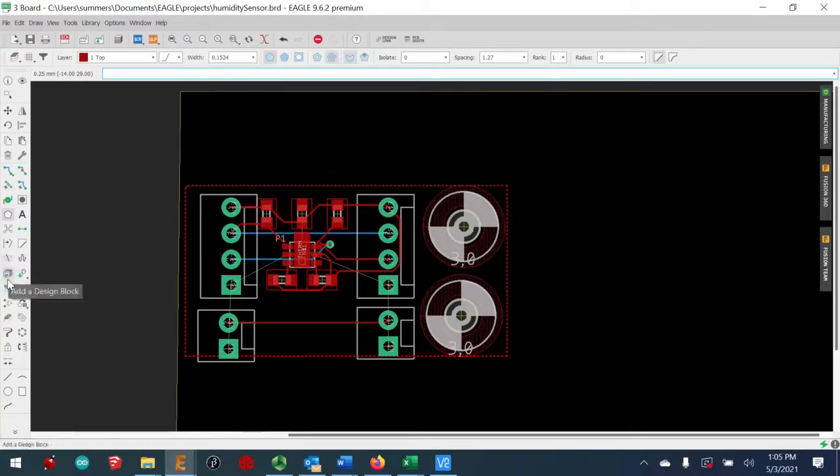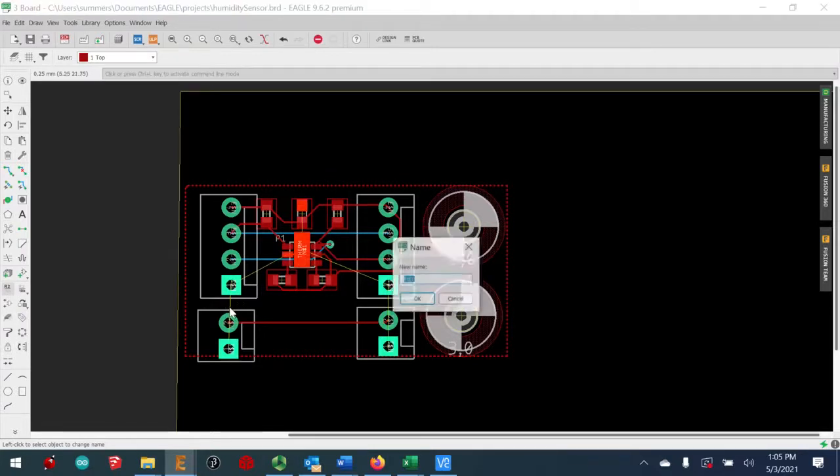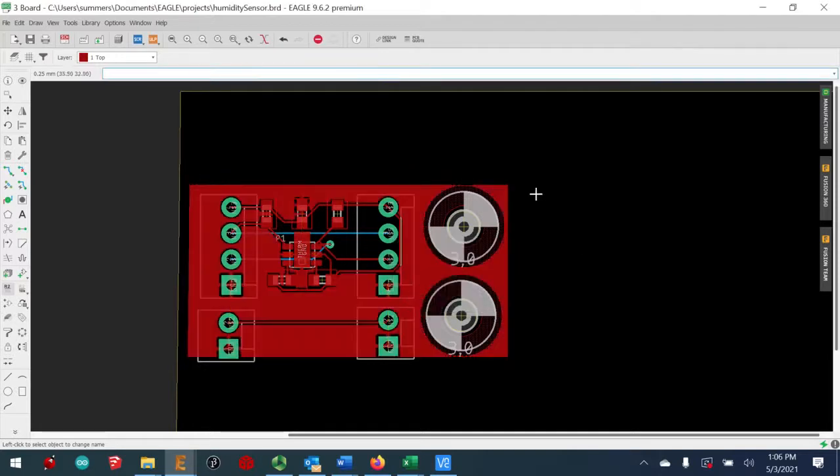And you do that with the naming tool. In the naming tool, it says R2, right? So we're going to click on that air wire there. We're going to call that one ground, GND. Okay, and you can see that lit up most of the top in red, okay? So all that red stuff is one big ground plane.